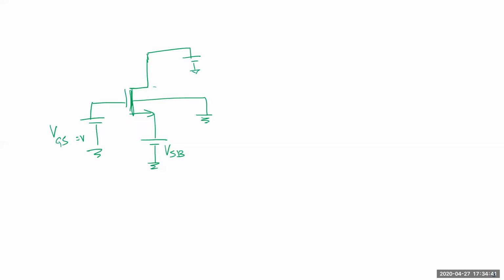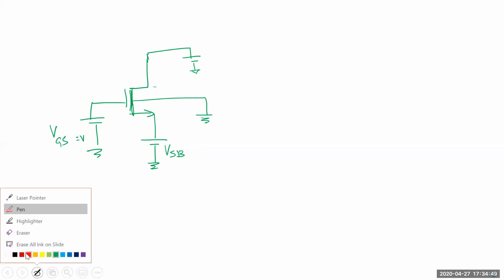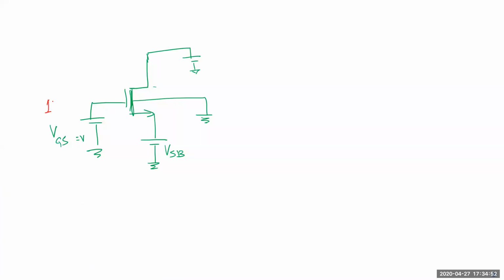So your question now is, let's say for example, the example you gave, we started with 1 volt, and let's say VTN was 0.9 volts. So a channel was formed. Now let's say I put 0.5 volts. Your question is, why is it not 1 minus 0.5? So I just compensated by doing 1.5 and then minus 0.5. It's still VGS is 1 volt, and then we are back into the same deal. Is that what you're asking?